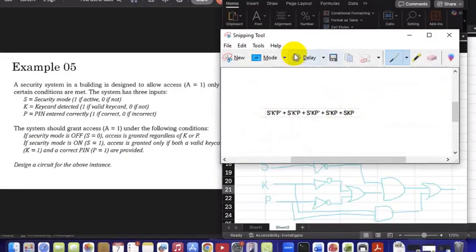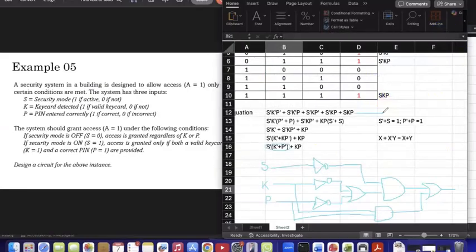So see, when you want to implement this particular one, you will need more number of gates. It takes time. It's not only about the cost, even when you pass an input, there is some propagation delay, like whenever the signal passes, it has to identify what is coming, and all this takes some time. So to make the system efficient and more affordable with less price, we always reduce and draw the logic circuit. So if I give a question like this, can you do it?